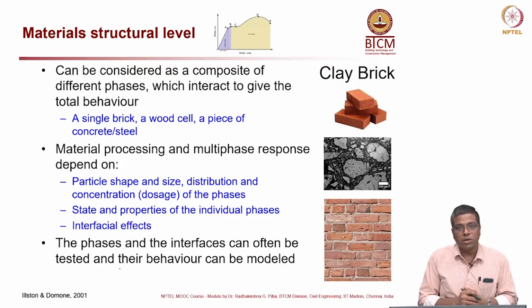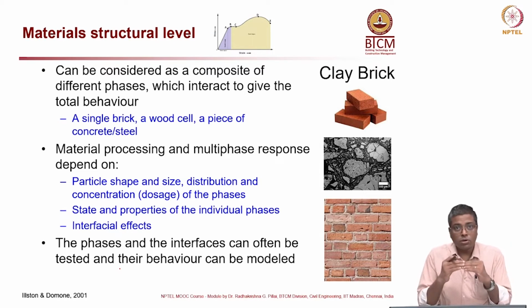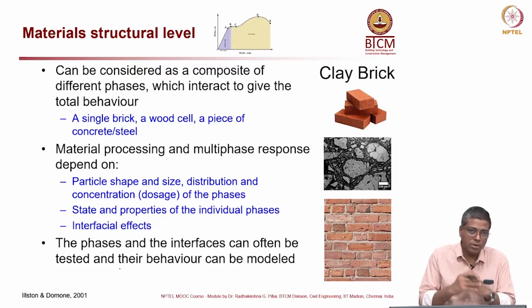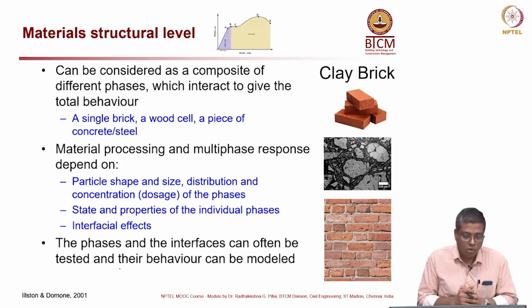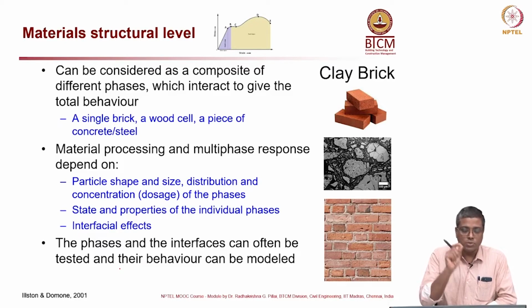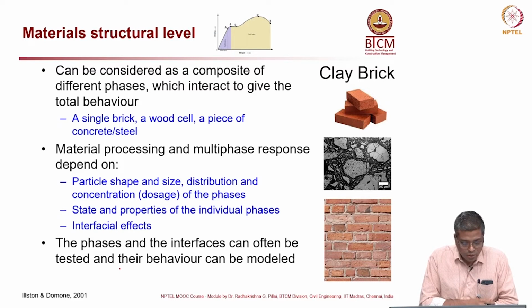And in the third picture on the right side, the bottom right corner, you can see the interface. When you talk about a clay brick wall, you also have to worry about how the mortar in between each brick is bonding or binding the clay bricks together as a single wall unit. So all these interfaces, how the properties at the interfaces are, that's also very, very important, in addition to the interface between the various particles within the clay. Okay. Now, the phases and interfaces can often be tested, and then behavior can also be modeled.